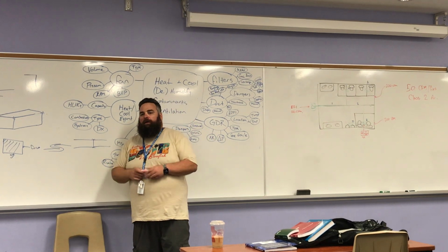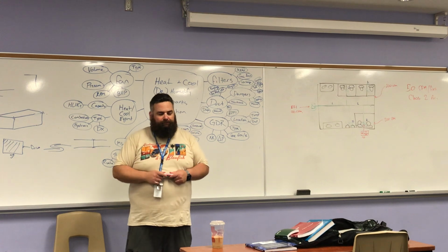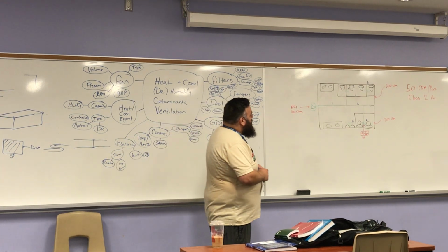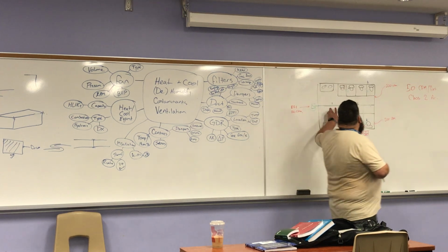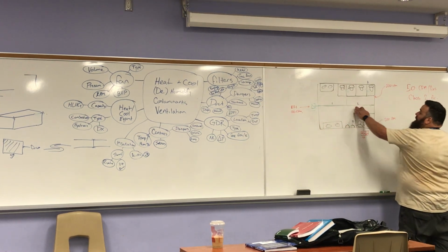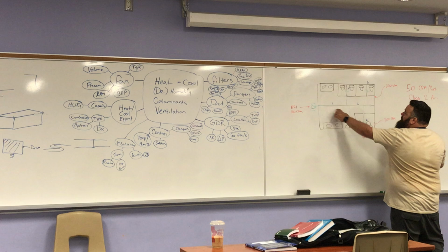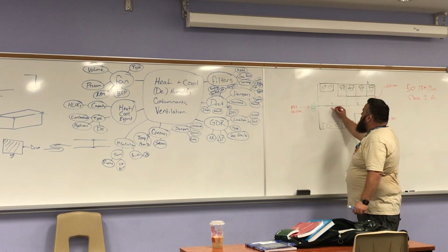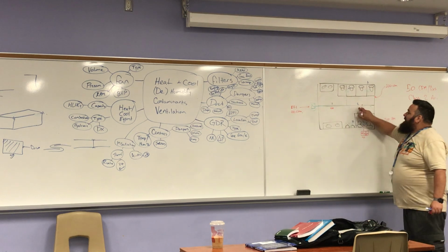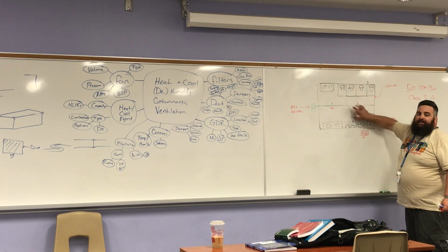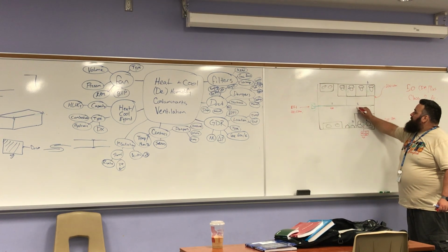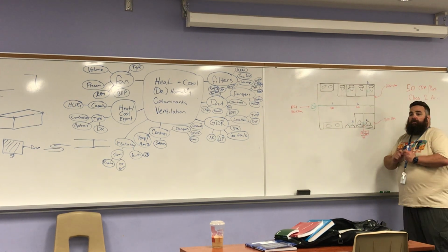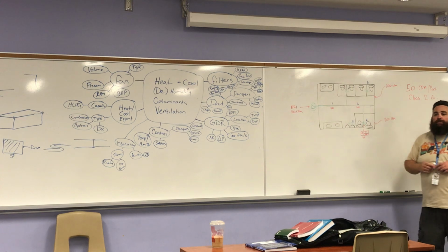We're going to focus on the equal friction method. Now I've split this up into 2 trunks. The first is going to see 400 CFM, and then the second, after C and D drop off, sees 200 CFM. Why might I split that up into 2 trunks?